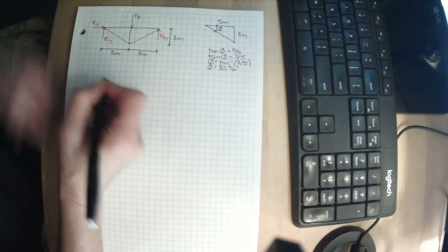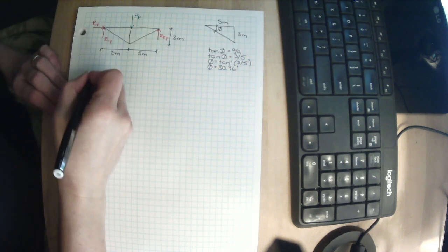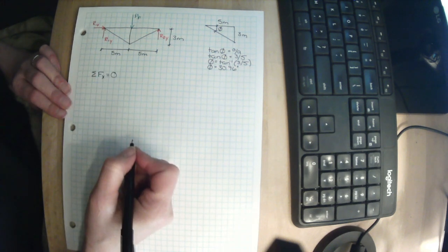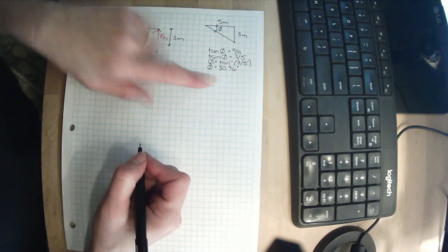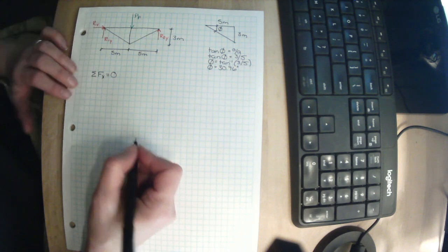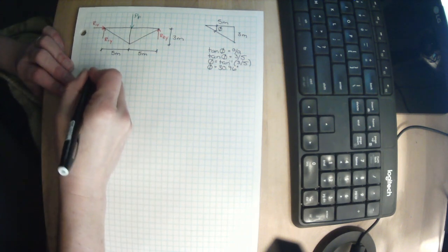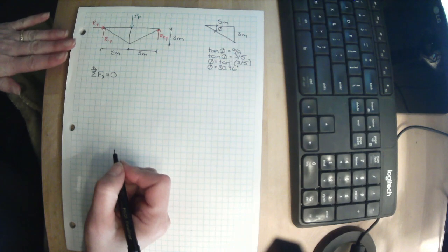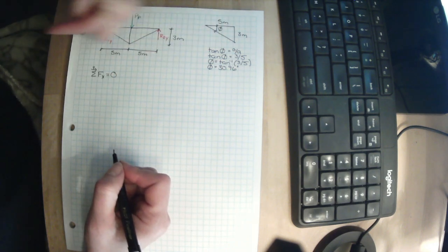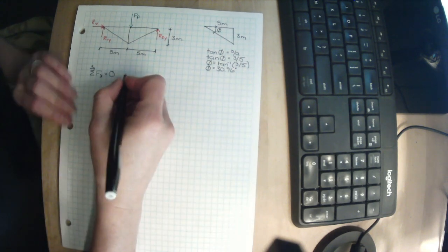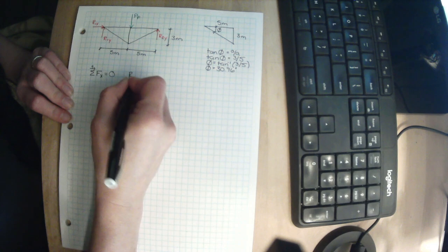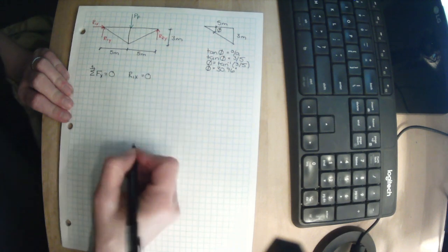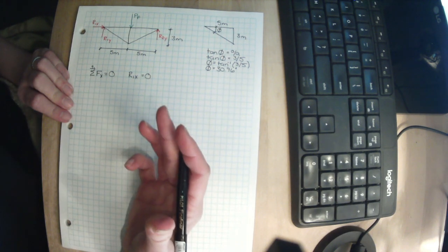So we know for it to not be sliding back and forth, the sum of all forces in the x direction must be 0. If there was any load pushing in that direction without something stopping it, it would move. Now, I find it always handy to remind ourselves that x is this direction, and anything in that direction is positive, meaning anything in the opposite direction is negative. So let's sum up all the forces in our x direction. R1x, oh, that's it, R1x equals 0. That was easy, wasn't it?